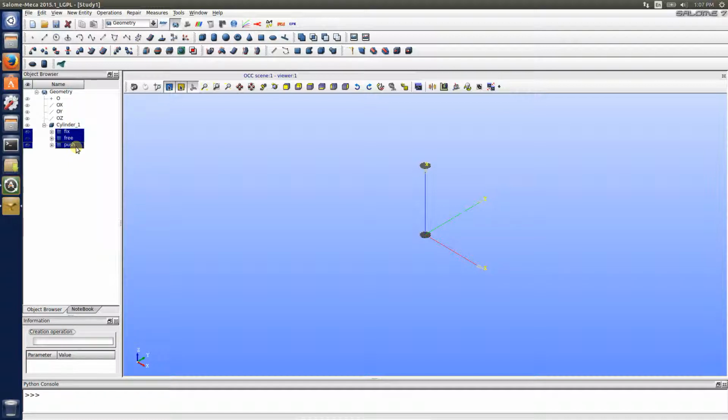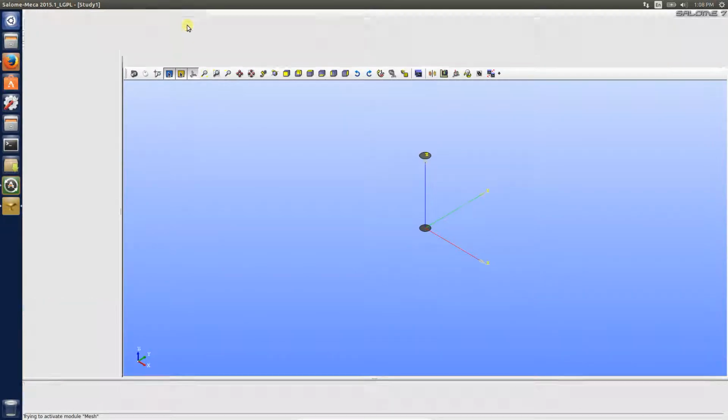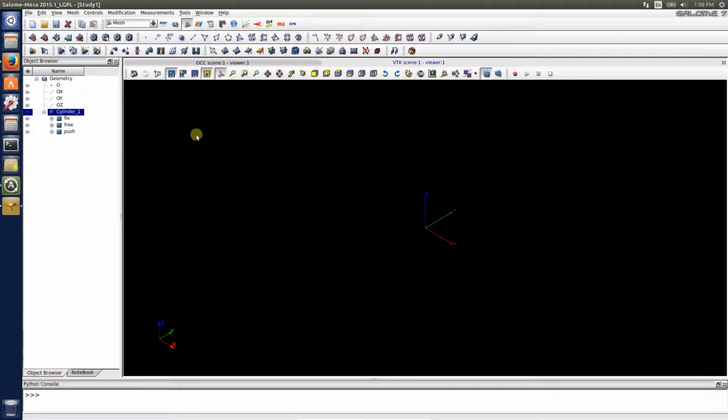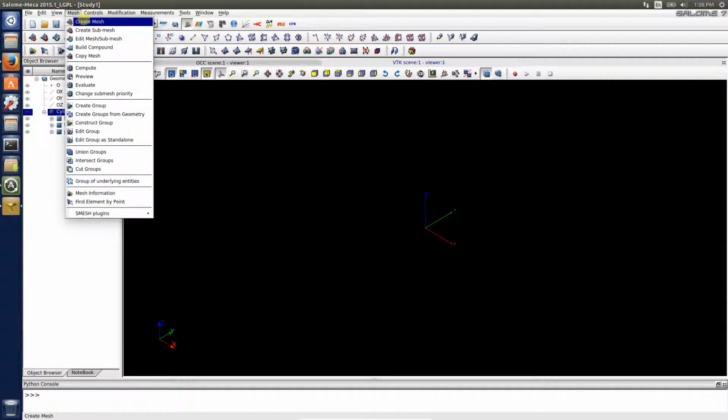So the first thing is to find the ones you're going to load and the one you're going to hold. Label those, and then label all the rest free. If I do that, I'm fine. I'm all happy and I'm done, and then I go to the meshing part. Hang on for a second. Then go in and create a mesh.